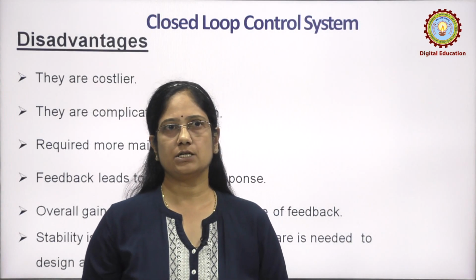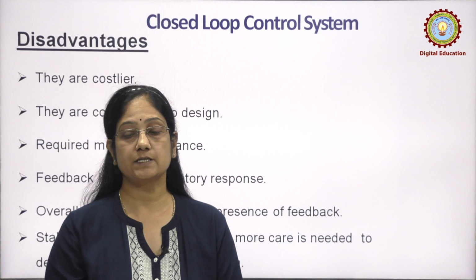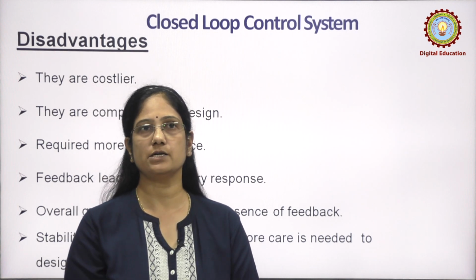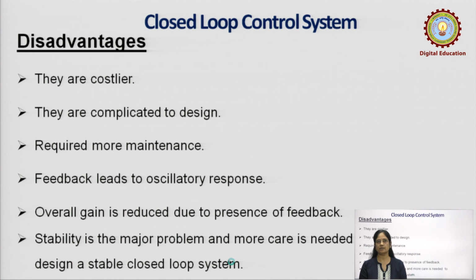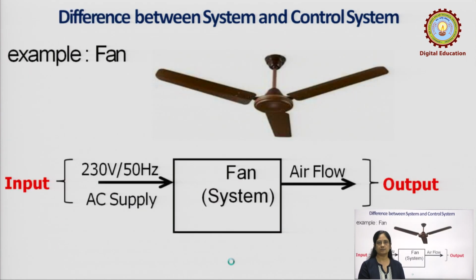Now, these are some of the disadvantages: obviously the design is difficult and it is costlier, the number of components has increased, and overall gain is reduced due to the presence of feedback. We will see over the duration of the course how feedback affects the system performance both positively and negatively. And stability, as I said, is a major concern in automatic control systems, which will be dealt with in time and frequency domain analysis, and of course it requires more maintenance.